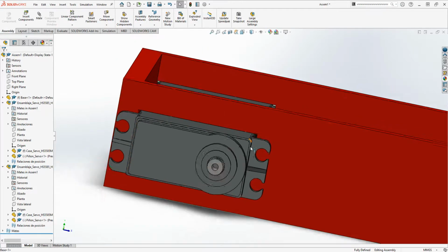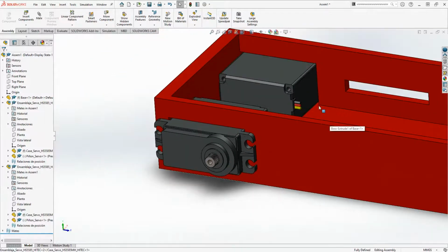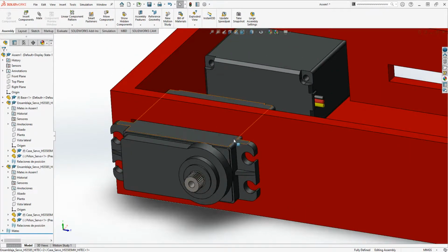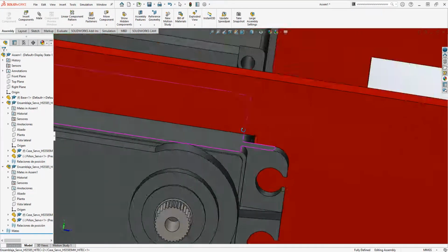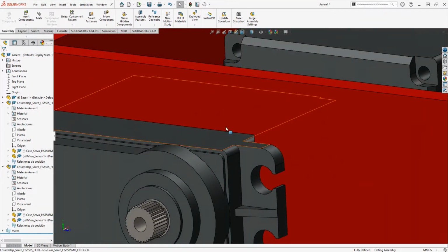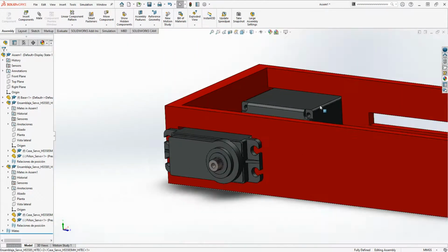Due to the nature of 3D printing plastic, which I would probably use to print this base that you can see here in red, those printing materials might expand during the cooling process, or as they get laid down, they might be slightly misshapen. Point being, if you design this motor slot to be a certain size, and then you make it exactly that size, you won't actually be able to fit the servo motor in.